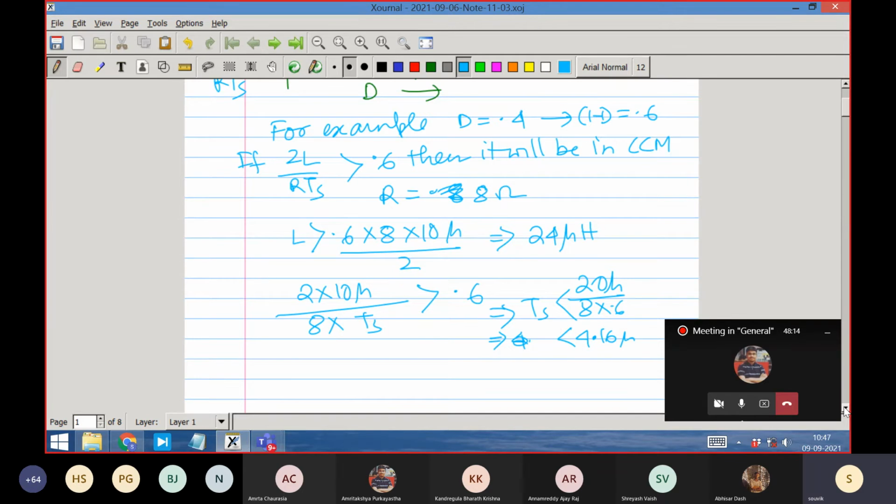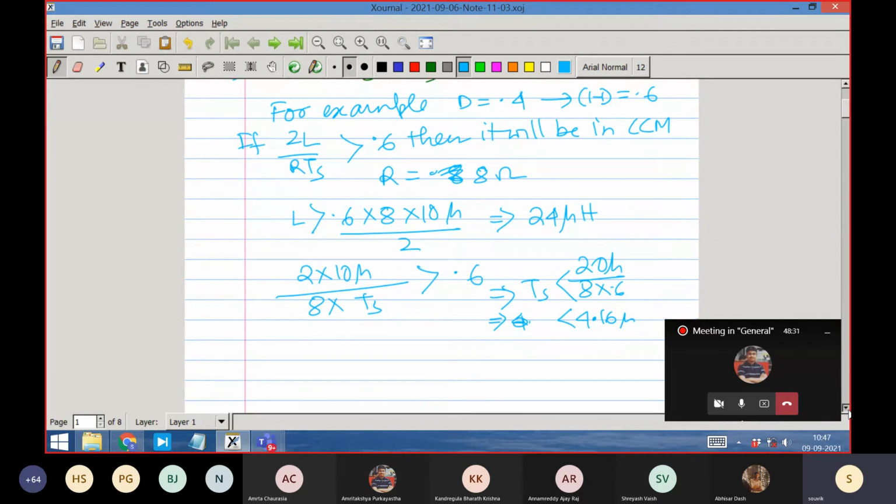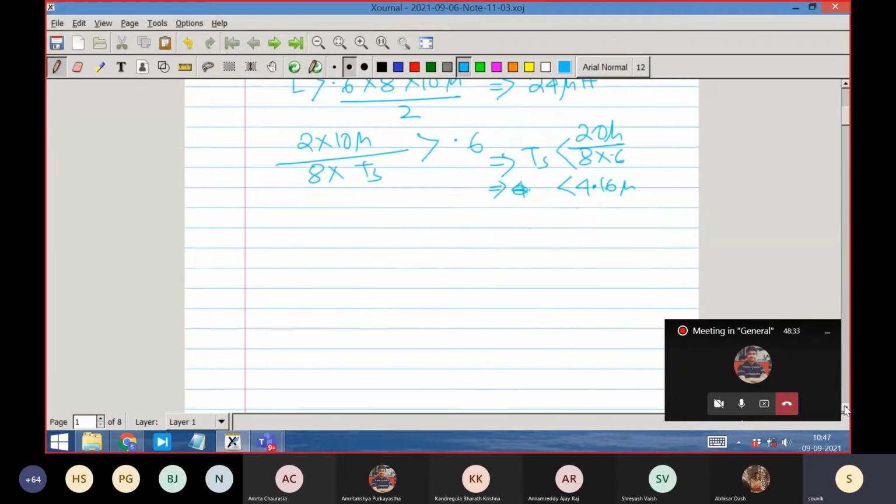Always remember the first equation. For the current ripple, you always look for an expression, L V is equal to L di by dt. So that is where you will get the delta IL. C dV by dt is equal to IC, from where you will get the capacitor voltage ripple. That means that we have to find out the capacitor current waveform in the discontinuous conduction mode.